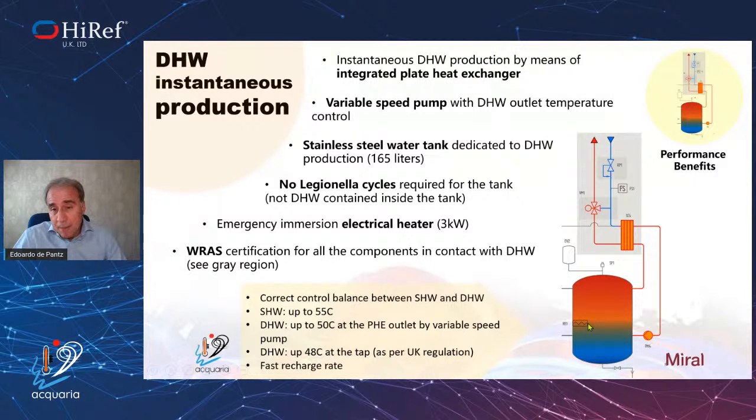There is also a backup heater as an emergency. This backup heater is not working during the normal function of the unit for domestic water production, but only in case of emergency. In any case, the Legionella cycle can be activated for service reasons if there is a request, but not for the normal functioning of the unit.